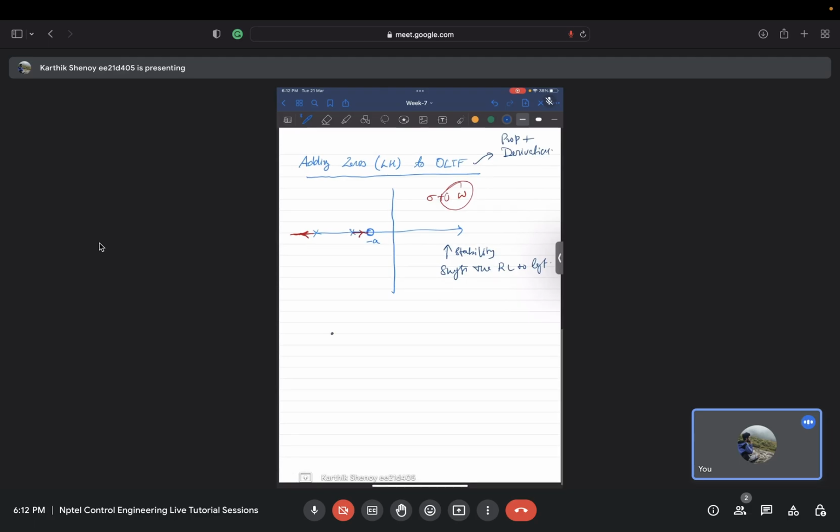Or take the car problem. If I want to stop here, I might overshoot, and this is the middle of the road, right? There is no integral action. If there is no integral action, then instead of stopping here, I'll have a steady state error of this much. This is bad. If it's an autonomous driving car, let's say it overshoots, what will you do? You can't, right?